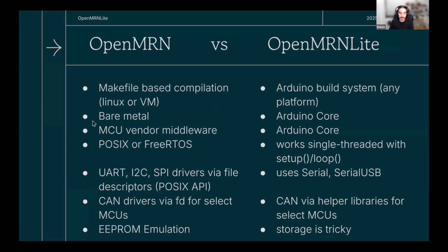Applications that are built on OpenMRN always work on bare metal. So we start with interrupt vector tables. We start with booting the processor. We start with setting up the clock. There is absolutely no operating system around that. For you using the Arduino environment, the Arduino core takes care of actually booting the microcontroller. And whichever microcontroller you're using, the respective Arduino core takes care of that.